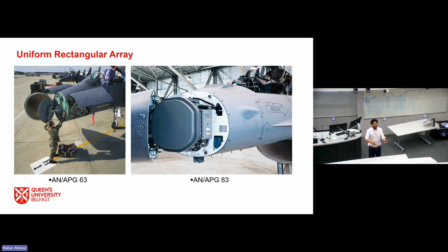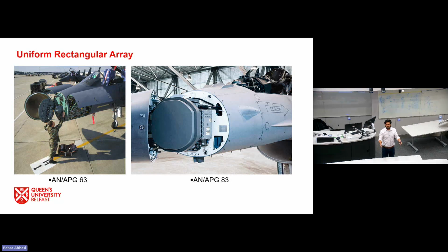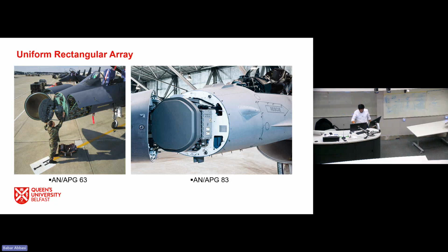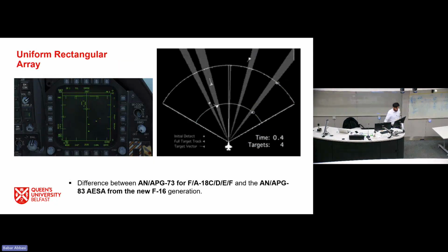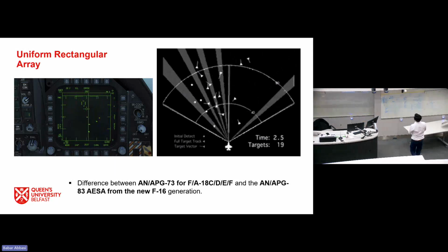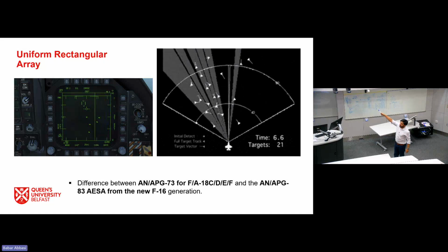So phased array means we have full control of alpha by 2 in a hardware setting. So if we have full control of alpha by 2, then we can actually tilt the beam in any direction we want, and we can do it in real time, so that this aircraft will definitely have very high speed. So the previous version was doing something like that mechanically, just to identify a friend or foe.